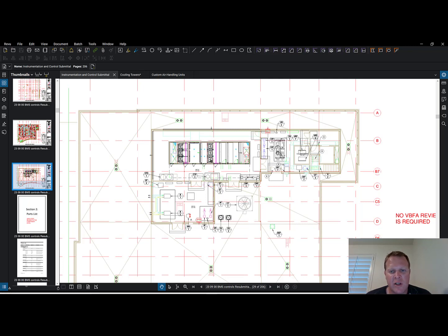How are you going to get this chiller up on the roof? Is that all crane? Well, how does that sequence with this penthouse? Do we have to get the penthouse roof built after the chiller? Do we leave out a section of the roof? Are these being brought in as sections? All early planning stuff that needs to be discussed, probably even through estimating a little bit, all the way back into there, how we plan to do a little bit of this penthouse on the roof.